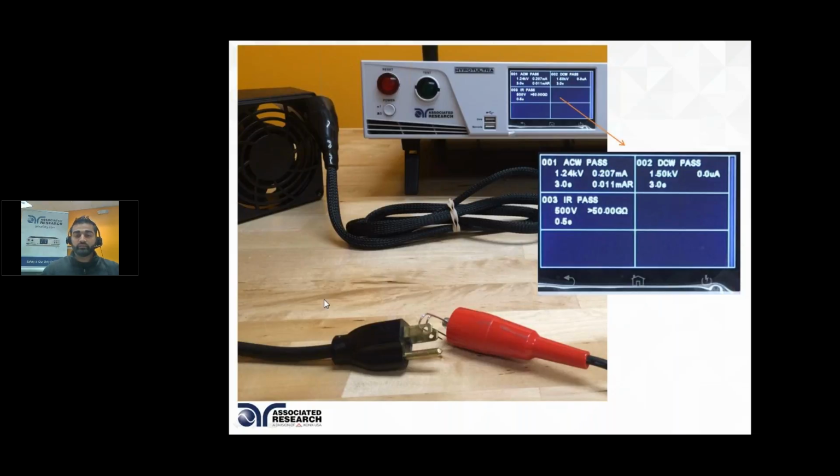So what that's telling us is that when this line and neutral are shorted and applying 500 volts here, the resistance to ground from that point to the chassis point here is more than 50 gigaohm. Or it is saying, on a high pot test, that if I ever encounter 1200 volts on my line or neutral, my insulation is good enough to not allow any current to flow to the chassis of the product. And you can see it's 0.2 milliamp. This is a rare scenario where you might have transients on your line voltage.